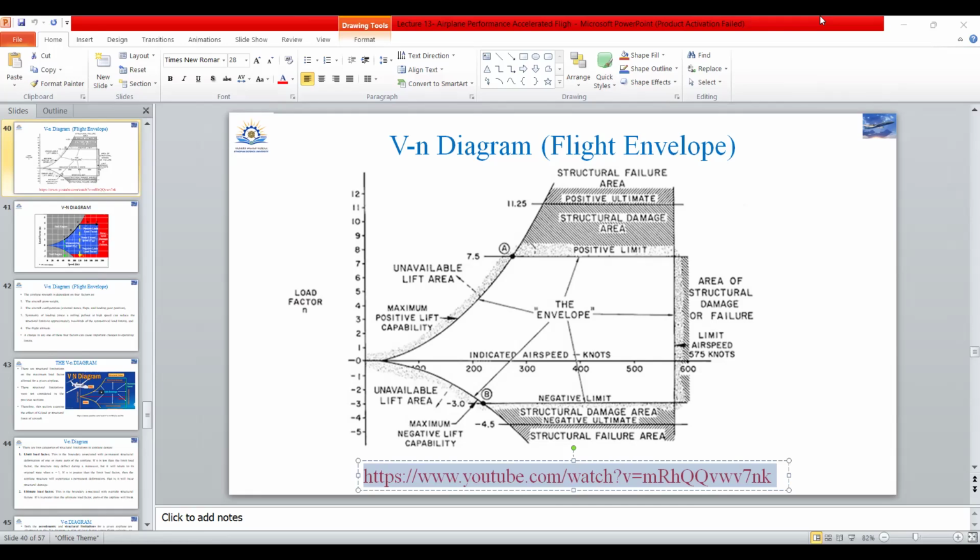When an aircraft is in flight, the structure is subject to different loads. Limit load factor is the maximum load factor up to which an aircraft is designed to operate. The strength of an aircraft and the materials used for building the aircraft depend on this load factor. In the VN diagram, these curved lines are the maximum positive and negative lift capabilities of the aircraft. For a particular aircraft speed, the load factor cannot be more than this G value, because the aircraft will stall.